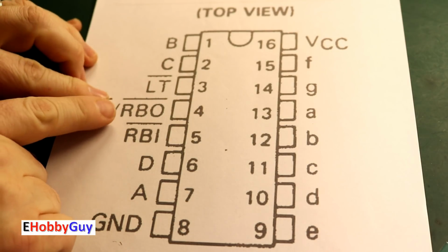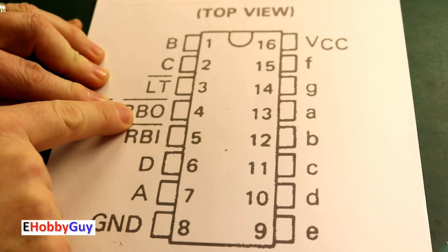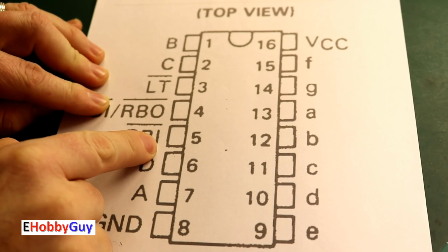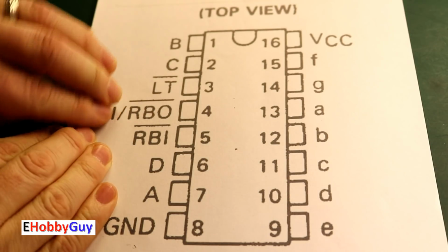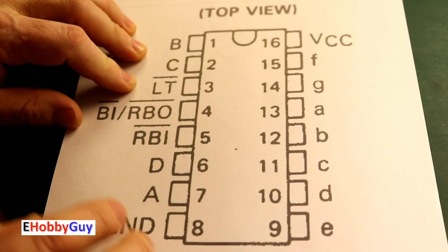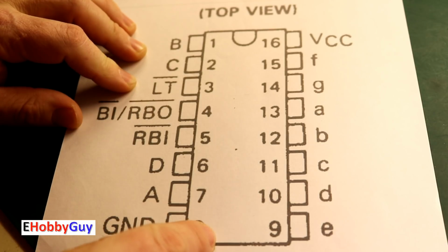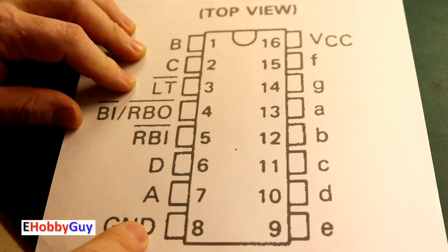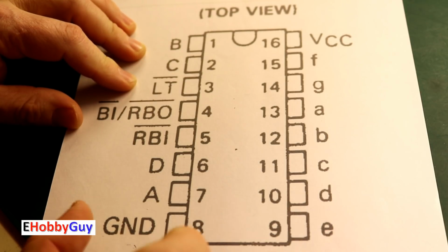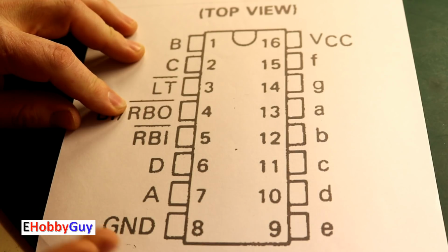So now looking at the RBO and the RBI pins on this chip. RBO, ripple blanking output, ripple blanking input. The word ripple refers to the zeros that are insignificant in front of the actual number that matters. And so let's say you have a 5-digit number that reads 00051. It's much more pleasing to just look at the two digits that matter, the 5 and the 1, lit up. And so we'd like to get rid of the preceding 3 zeros, and we can do that with these. Those zeros are the zeros that are rippled forward.